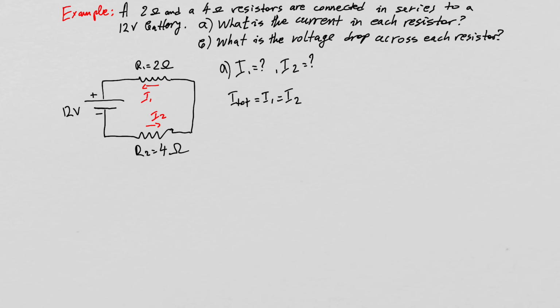So then the other way to go about solving the problem, which will give me a result, is to determine the total current in the circuit. I can find the total current in the circuit because I know the voltage supplied by the battery, and I also can calculate the total resistance of the circuit using the resistances of those two resistors.